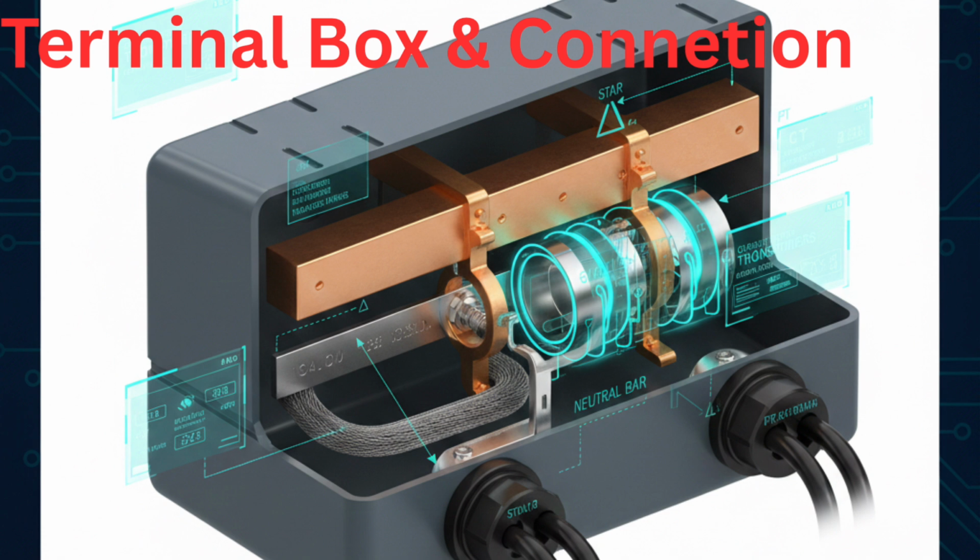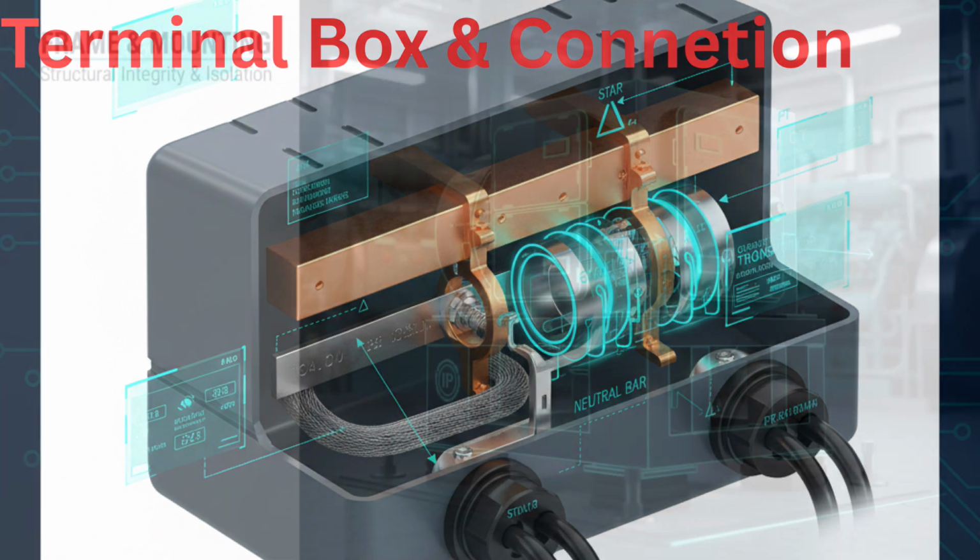Heavy-duty cable glands and sealing arrangements protect against moisture ingress. Engineers must regularly inspect terminal boxes for loose connections, discoloration due to overheating, and signs of insulation breakdown.